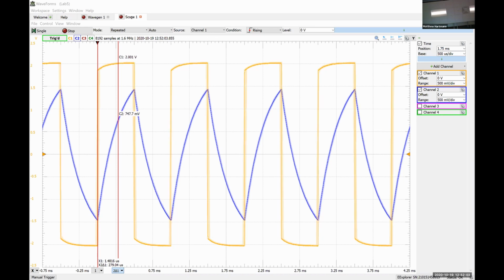What can we do to change our time constant? Yeah, we'd have to change a resistor value or something like that. There's nothing fundamentally that we could do to this circuit other than literally changing the components by saying putting another resistor in parallel or another resistor in series or adding another capacitance or something like that.